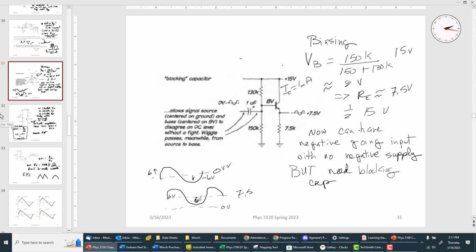What's the voltage at the base? And in fact, this was assuming 15 volts, right? So you have to do the calculation with 12 volts because that's the size of your power supply, right? So you can calculate that. Then you know what VE is, and in principle, that should be the center of your output. So you should check and verify that, right?